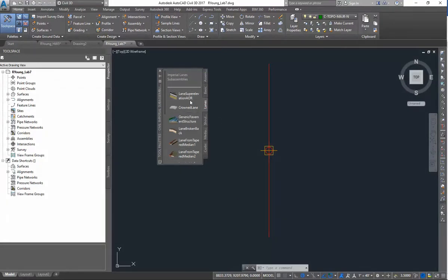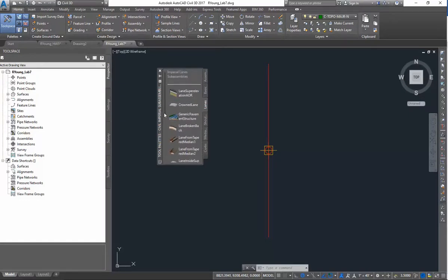The use of these defined objects to do your assemblies has a lot of benefits for calculating quantities, such as how much pavement or base or subbase material would be needed. There are a lot of properties associated with them. Not all of them are objects that can follow a super elevation view. So for our lanes, instead of using a basic shoulder or basic lane, we need to use a more advanced one, the lane with super elevation, meaning travel lanes using lane super elevation slopes. These support the rotation that's required for your tangent runout and your super elevation runoff. If you were to select a basic lane, it would remain static and wouldn't follow a super elevation table.